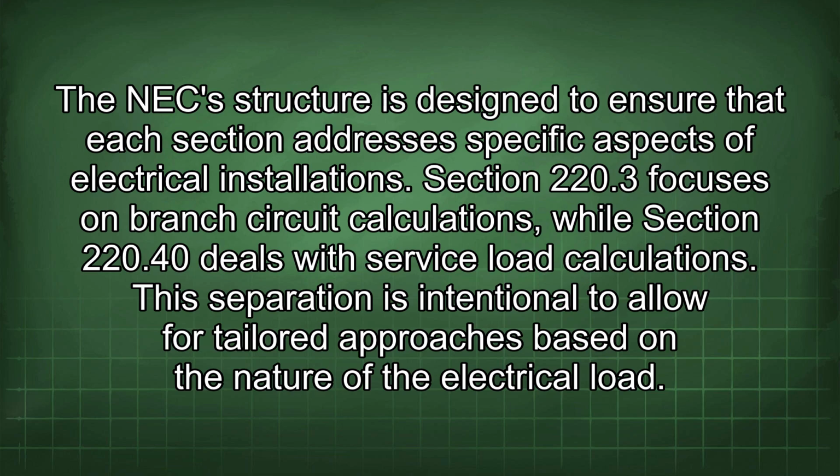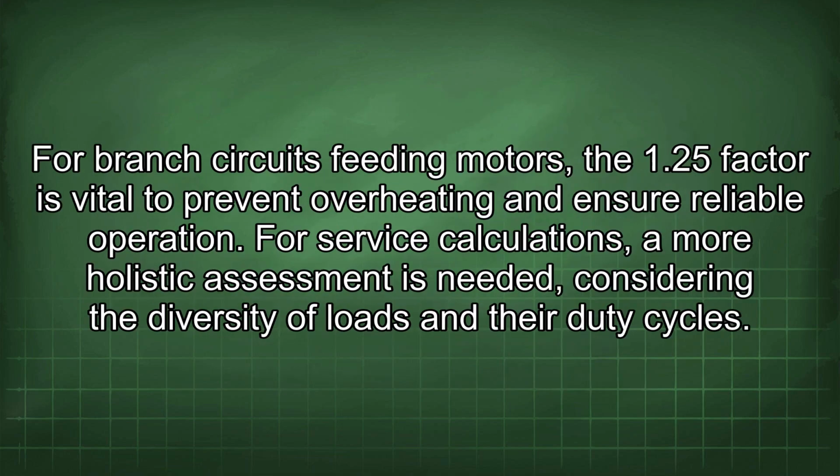The NEC structure is designed to ensure that each section addresses specific aspects of electrical installation. Section 220.3 focuses on branch circuit calculations, while Section 220.40 deals with service load calculations. This separation is intentional to allow for tailored approaches based on the nature of the electrical load. For branch circuits feeding motors, the 1.25 factor is vital to prevent overheating and ensure reliable operation. For service calculations, a more holistic assessment is needed, considering the diversity of loads and their duty cycles.